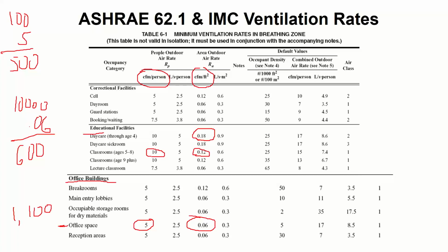The reason why we have 2 numbers, it used to be just 1 number until maybe, I want to say, 2004 for ASHRAE and 2006 for IMC. We used to have 1 blended number, but now we have the 2 separate numbers. And the entire reason for that is to separate them so I can control them differently. We talk about demand control ventilation in a little bit.